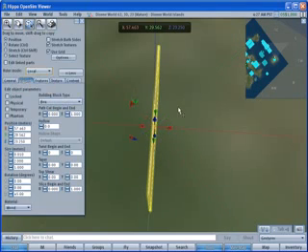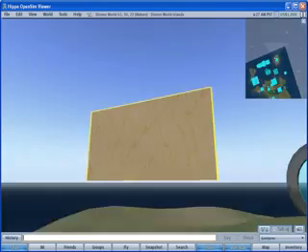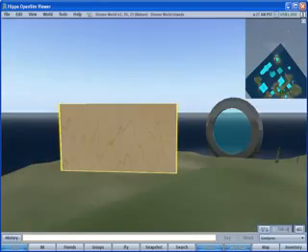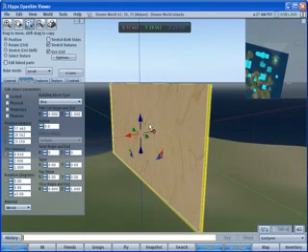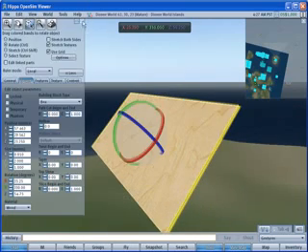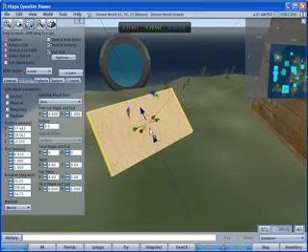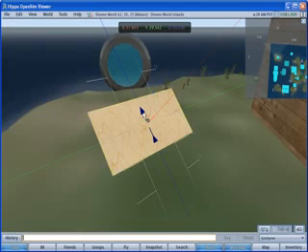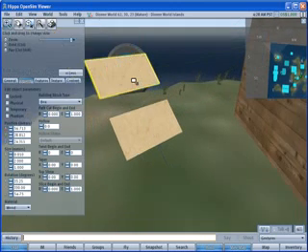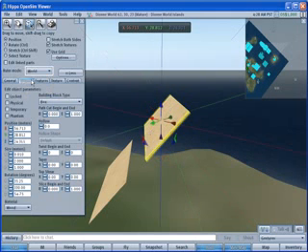Now, one of my favorite things to do is enter local mode. You see here, it ignores the world coordinates and allows you to manipulate the object based on its local coordinates. Observe. See that? Nice, huh? Now, one last thing. Copying. If you hold Shift and drag the position axis out, you will copy the object in any direction. Well, ideally the direction that you were dragging it in, of course.